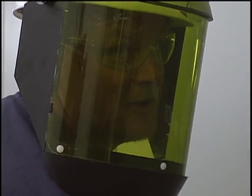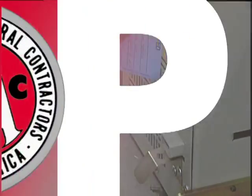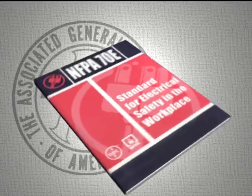Wear safety glasses or face shields when exposed to any electrical hazards, including work on energized electrical systems. Be sure to consult the applicable National Fire Protection Association 70E tables for the appropriate protective equipment for these hazards.